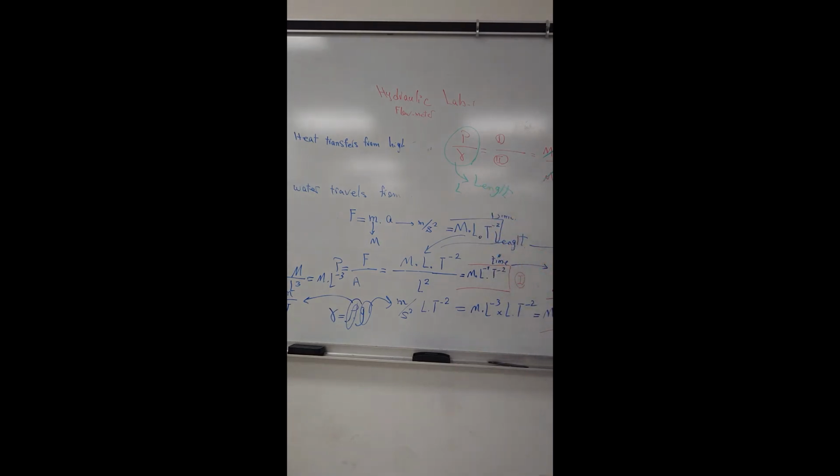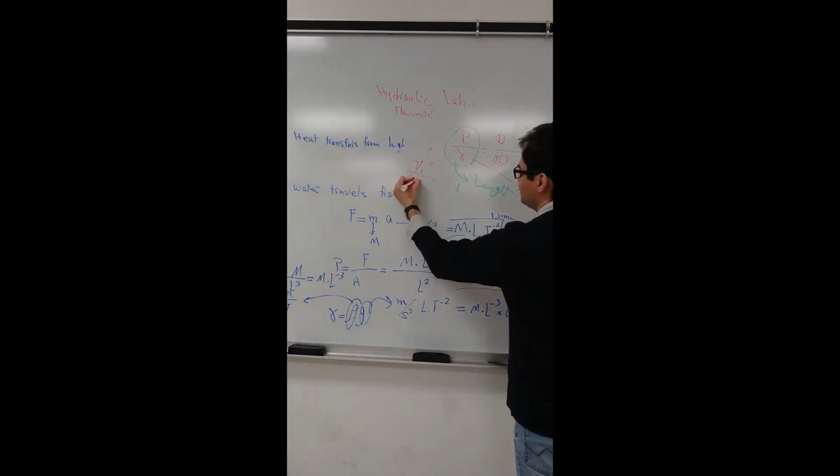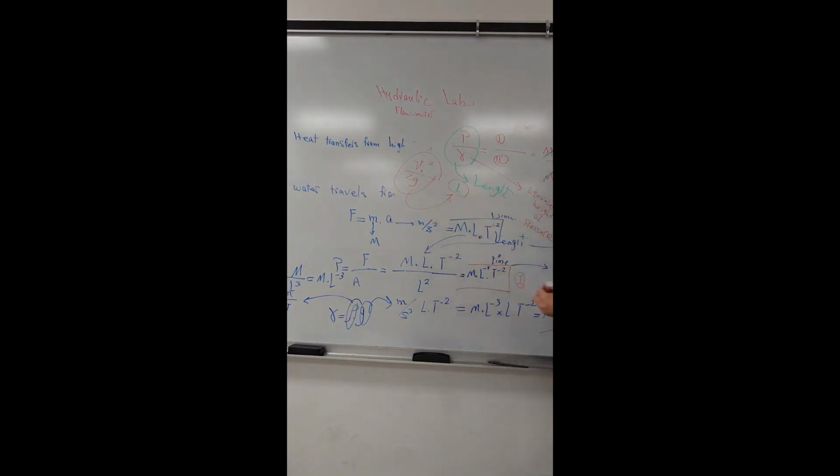That's why we call it equivalent height of pressure. If you do the same thing for the third term of Bernoulli equation, which is V1 to the power of 2 over 2g, again you reach the dimension of L, and this time we call it equivalent height of velocity. These three components are the major contributors to Bernoulli equation.